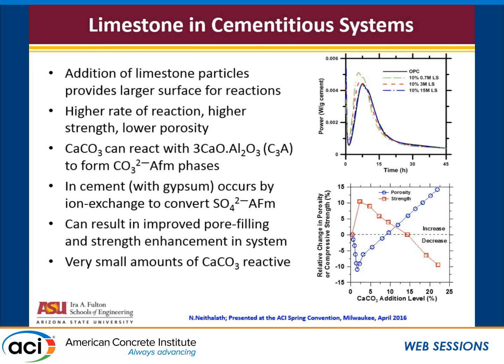That carbonate-sulfate balance now becomes key. So basically what it effectively means is you can't have the same cement with the same gypsum content doing exactly the same thing if you replace 10 or 15% of that cement with limestone. So now that becomes another balancing story.